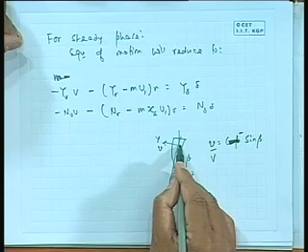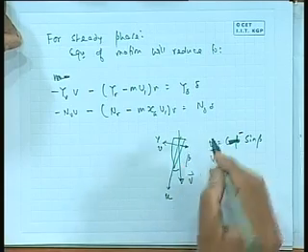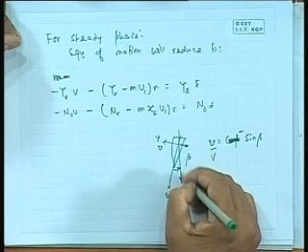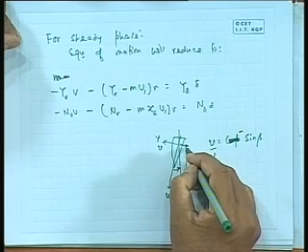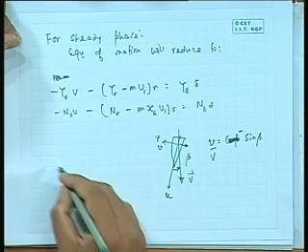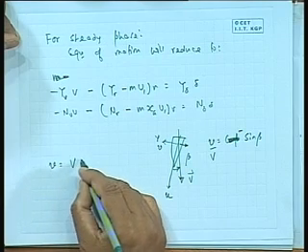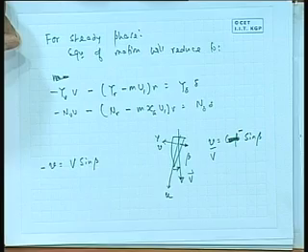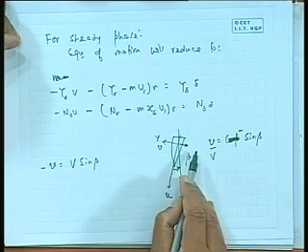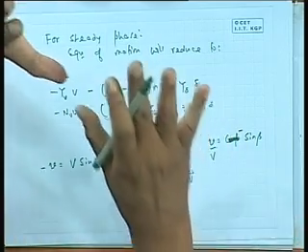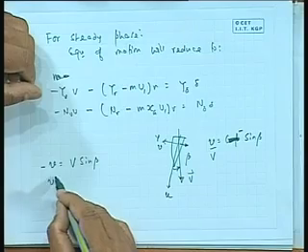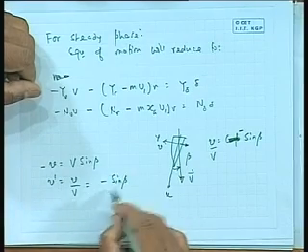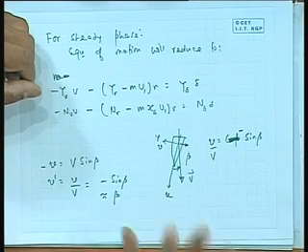So actually in this case, if my beta is positive, small v happens to be big V into sin beta with a minus sign. Why minus? Because when beta is positive, v is negative. I don't want to go into the detailed part of it, but my definition of v dash is equal to v by V. Therefore, it becomes minus sin beta. This becomes equal to minus beta because beta is small.